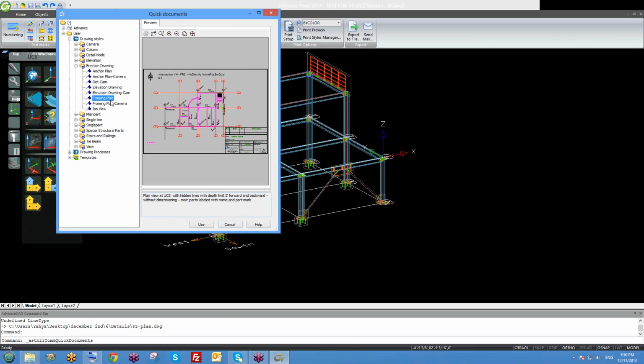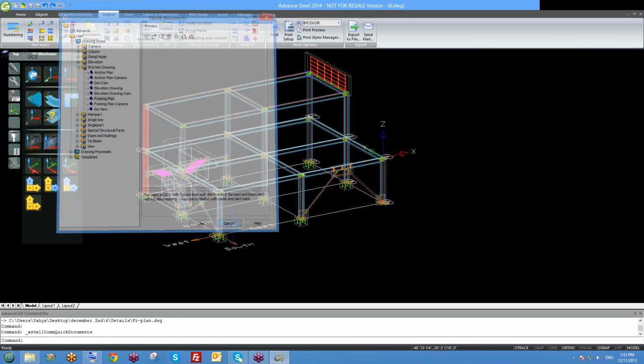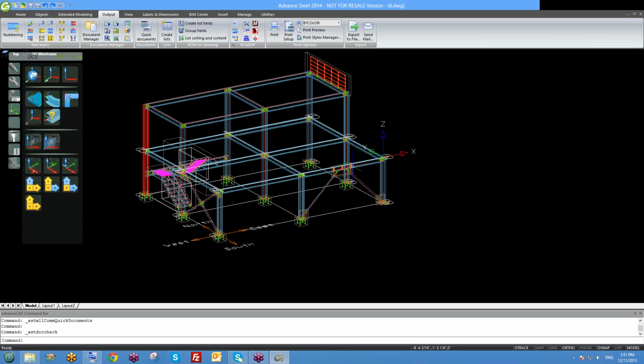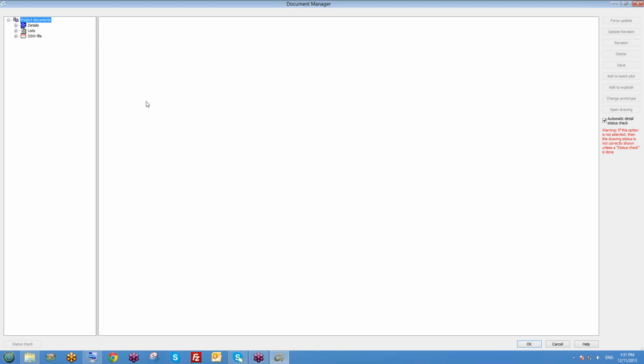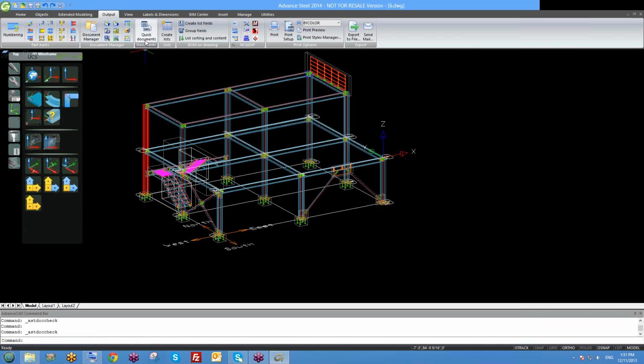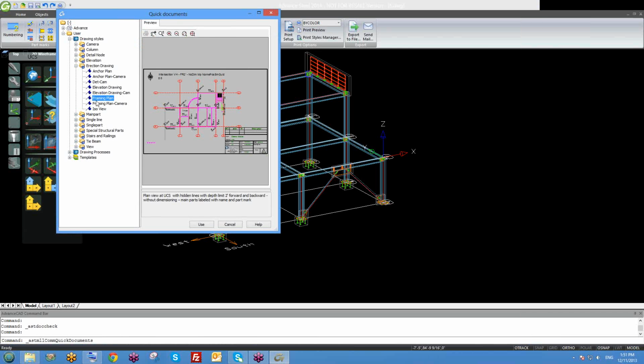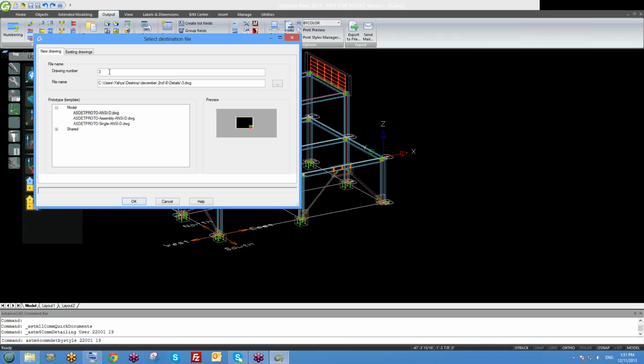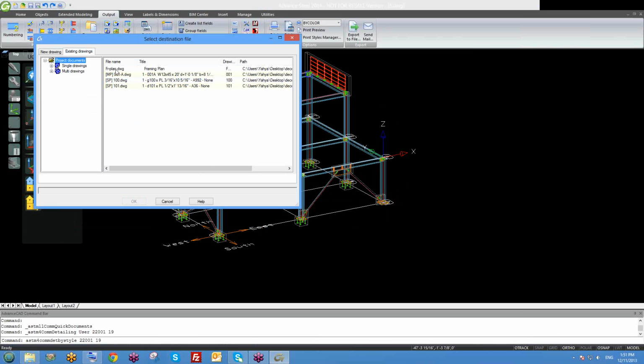Now I got a question for you. Go ahead. My drawing that I used, can I place certain erection views on the same drawing? Yeah. Because it's going up to my other number. So where I say drawing number, can I say 5 here and put it on the same one? Yeah, of course, it'll put it on the same one. Once you click on framing plan, you click on existing drawings and put it to the one you generated before.